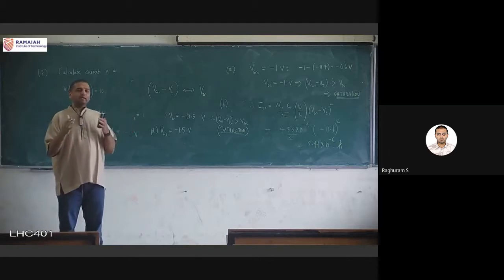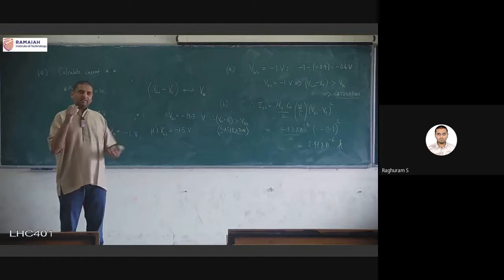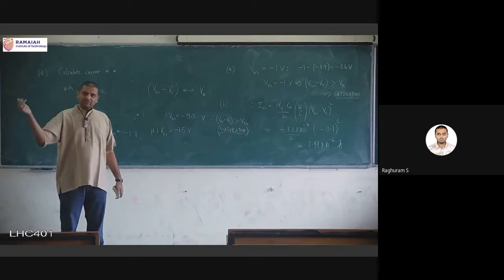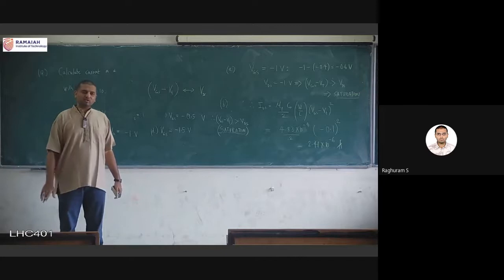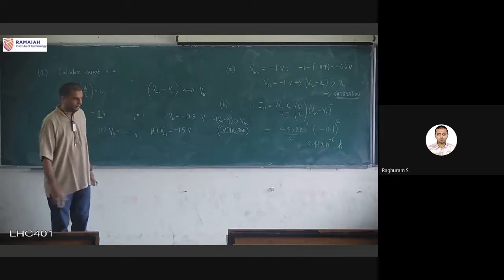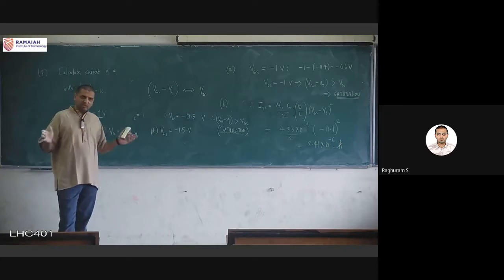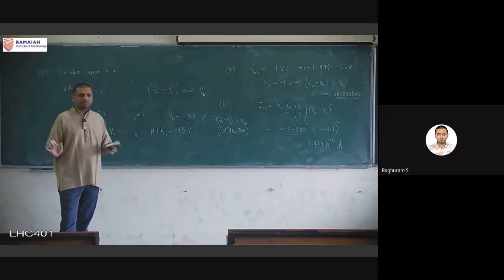Whenever you want to go from linear to saturation, in that equation, wherever you have the term VDS, if you replace that with VGS minus VT, you will automatically get the simpler equation, which is the saturation equation. So you don't have to remember everything, just have some tricks which will help you remember fewer things, but you will be able to solve the general class of current calculation.